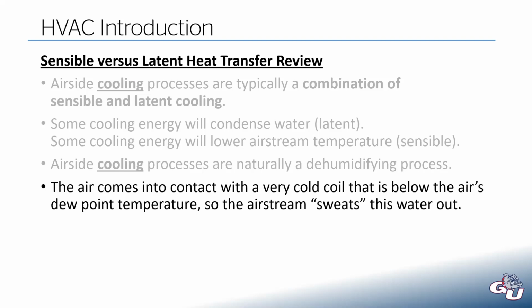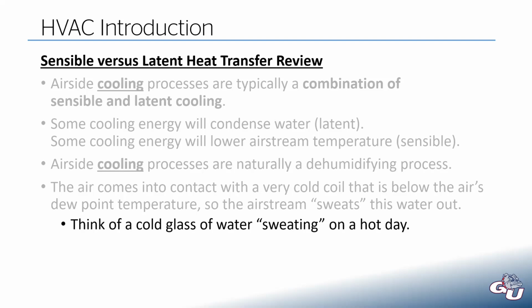So if you think of a cold glass of ice water sitting on your table, if you let it sit there, the outside of the glass will sweat because the glass is below the dew point of the surrounding air. Similar concept here. Our airstream is hitting an extremely cold coil, and so the water vapor in that air is going to condense out.